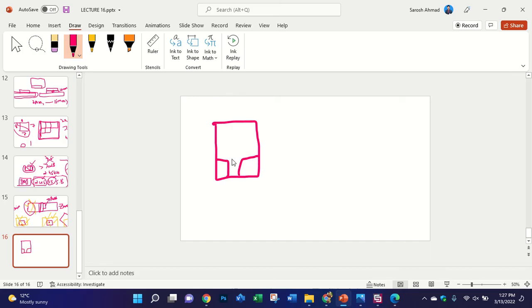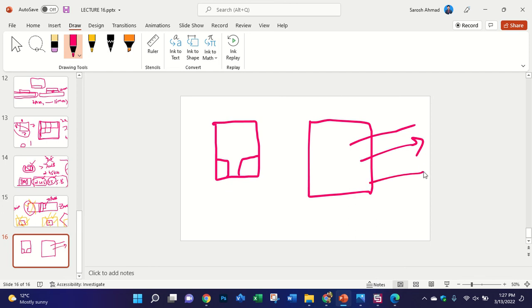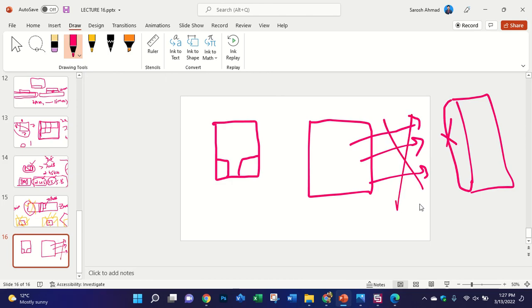Why? What is the reason? As you know, in the metamaterial, when we have a full ground plane behind the antenna, this reflector, this metamaterial, will not work properly. All the radiation is in this direction of the metamaterial, you have an antenna here, and there is a full ground plane behind the antenna, and this ground plane cancels this effect. So that's why. Does this make sense when you use a full ground plane?